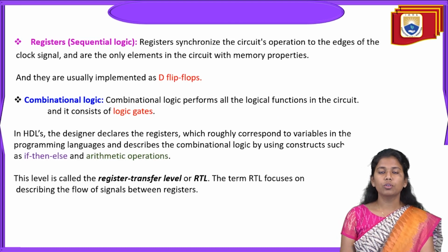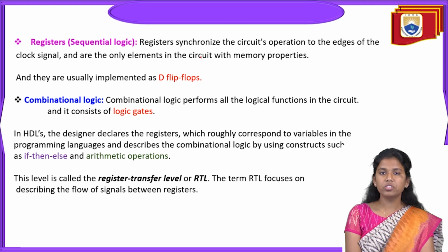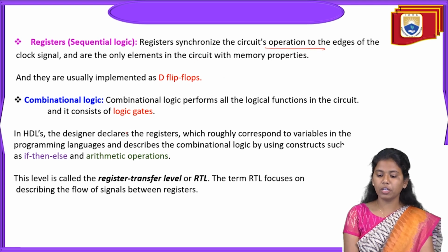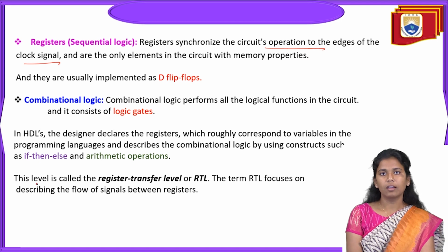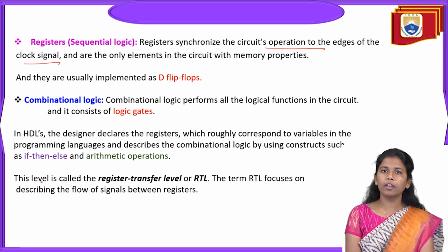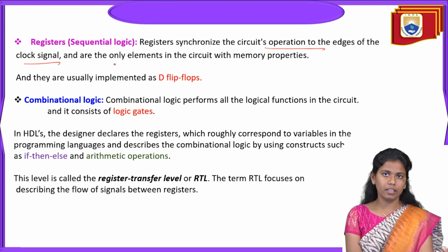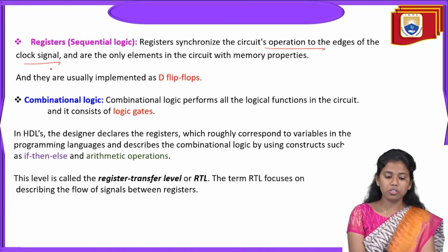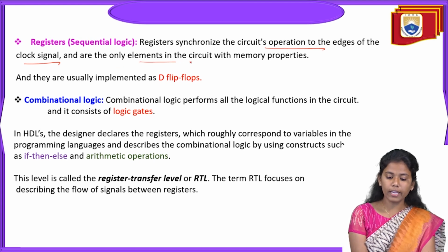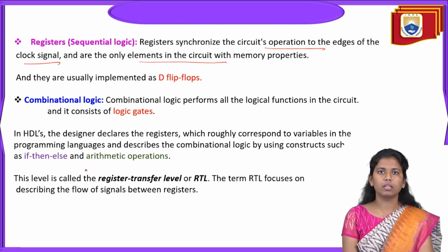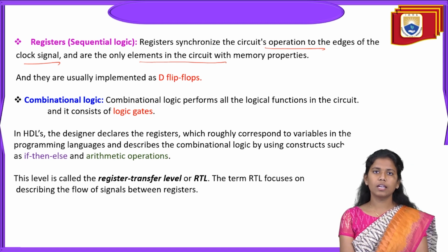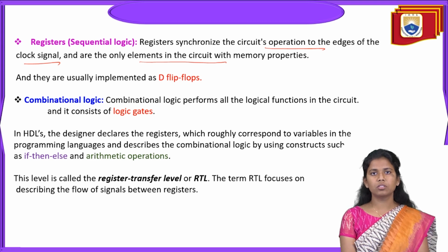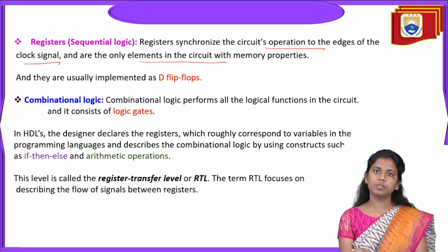So registers are a sequential logic, where the registers synchronize the circuit's operations to the edges of the clock signal. The key role that these registers, or this sequential logic, play in RTL is that they synchronize the circuit operation to the edges of the clock signal, and are the only elements in the circuits with memory properties. As I said, these registers are nothing but storage devices. Not only registers, we can go with flip-flops and latches as well.